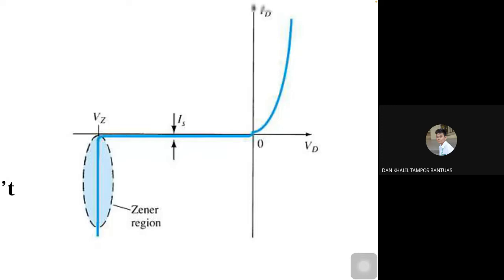So, what I showed earlier, those are 3 types of diodes. The first one, the black one, is the regular silicon diode or regular junction diode. The red one is the light emitting diode or LED. The other one, the small one with a transparent casing, is a Zener diode. So, the Zener diode operates normally at the Zener region. And if the Zener region is reached, the Zener diode will not break. It is its normal operation in the Zener region. But the regular junction diode, if it reaches the Zener region, it breaks right away.